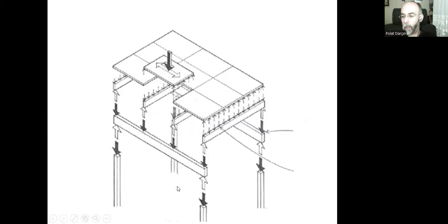And we mostly create buildings or structural systems as a skeletal system. In this example, we see its components. When we say a building structure, we are referring to the building element, and it has its components, such as horizontal beams or vertical columns, and the load transfer starts with the horizontal surface. In this example, we are referring to a floor, obviously, and then the floor is carried by the horizontal beams, and under the beams we have columns, vertical components.